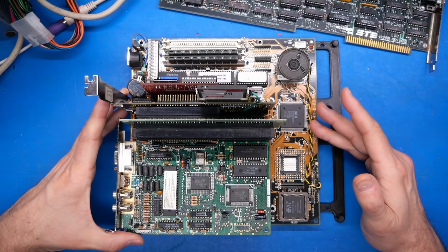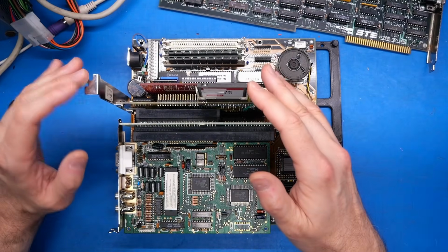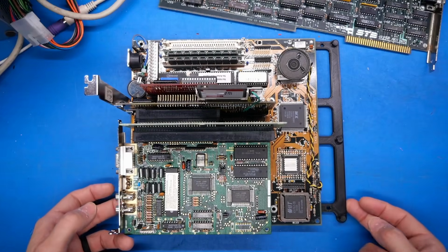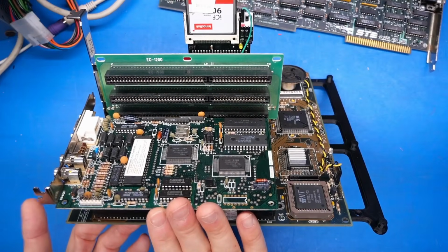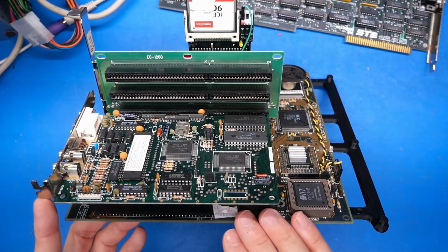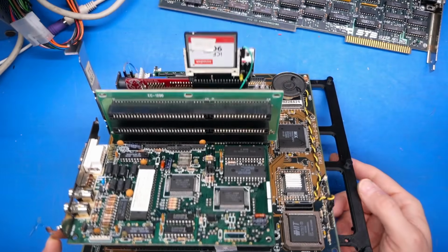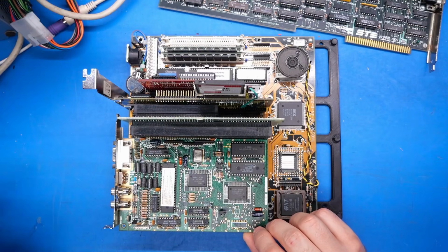It's a normal 36SX motherboard, the one you've seen on my channel many times. I have an IDE card in here with my compact flash card, XT IDE card for the BIOS, and then I'm just using a normal ISA riser card here so I can plug any ISA card into this and keep it parallel to the motherboard. So we can run this and do some testing on it while it's powered up and in use. Of course, this thing is sort of floppy right here because nothing's holding it up.